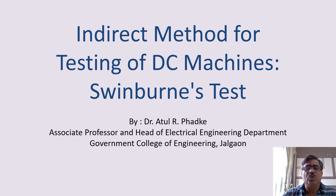In our last video, we have studied direct method for testing of DC machines. We have seen that direct method gives most accurate result, and we can also check conditions like temperature rise, commutation, etc. during actual loading condition with the help of direct testing method. However, direct testing method is not suitable for large machines. For testing of large machines, we have to use indirect method or regenerative method.